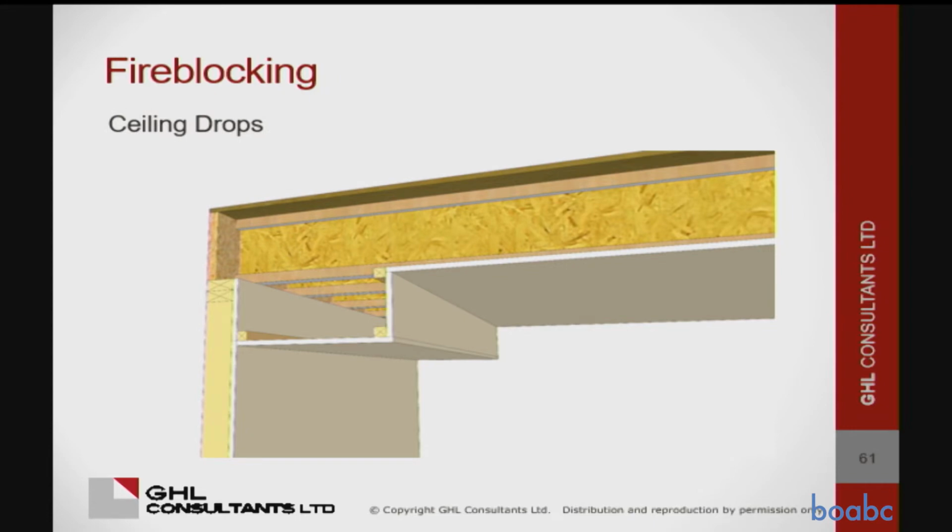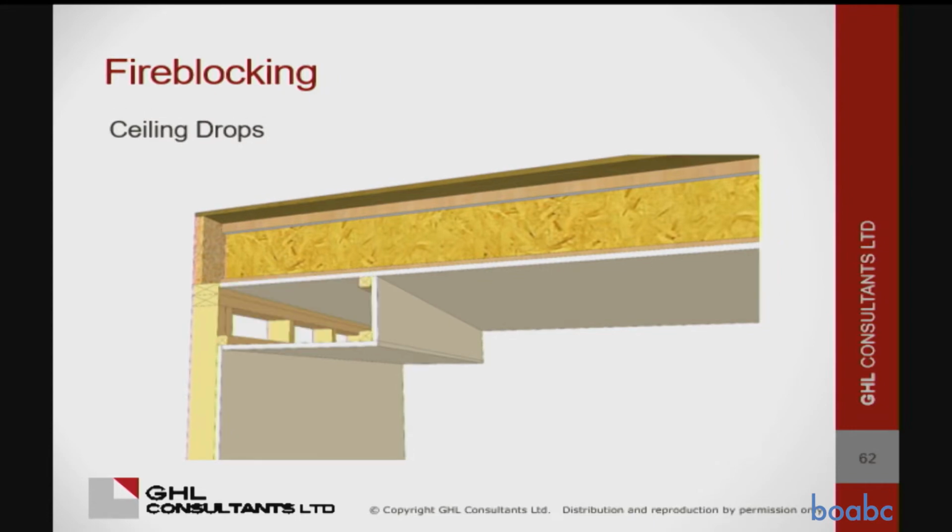But yeah, we had some interesting discussion on the previous two slides about whether you could do that. And maybe, depending on the size of the bulkhead, we thought, well, maybe if you use that 165 cubic meters out of NFPA 13, so you didn't have to sprinkler it, then maybe you could say. But it's going to be up to the individual, I guess, to decide whether that's an issue or not, or how big the space needs to be before you should do both.